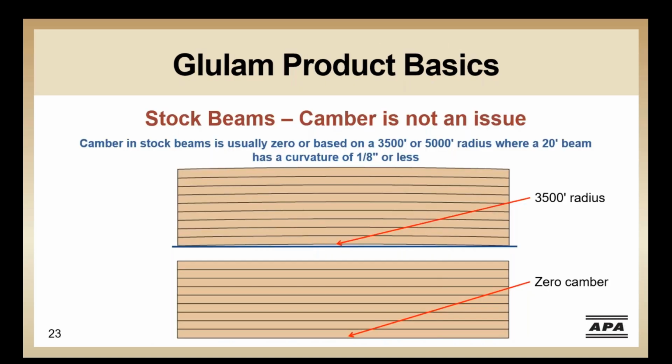As you saw in the previous slides, glulam beams can be ordered as a curved member for dramatic architectural effects, but they can also be ordered with a camber so that under dead loads the beam is flat. This is desirable for long beams such as ridge beams where the design professional will specify a specific amount of camber for these members to eliminate sagging.